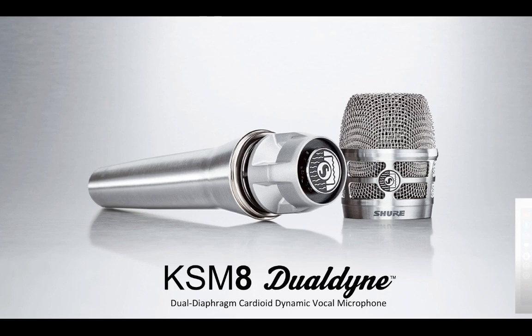And they stripped it down, and we knew from our KSM9 that if we could get a second diaphragm as part of the resistance network, as part of that side entry network of how to create a directional mic, we could control this proximity effect. The challenge was, on a dynamic microphone, how do you physically do that? Because you've got all this stuff in the way.